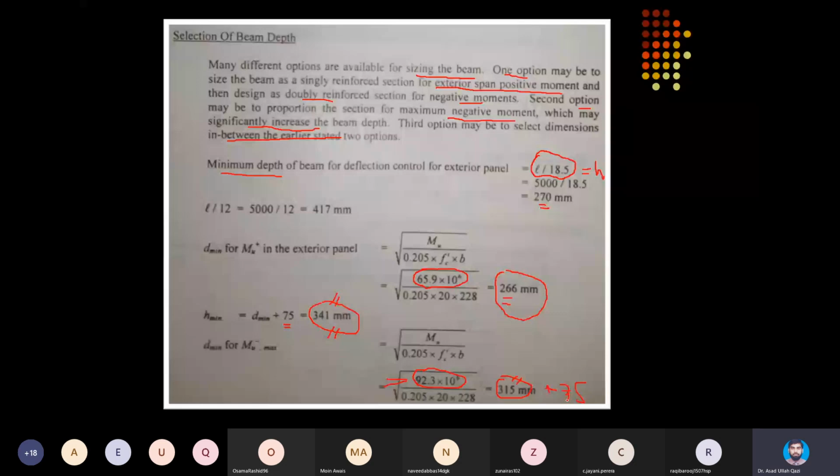You want to release some moment, then this much strain in the steel is required corresponding to crushing in the concrete. But just to keep the problem simple, and I am not at this moment discussing with you that possibility of redistribution, I am not following this recommendation. And from this slide onwards, I will be designing it more simple, straightforward.